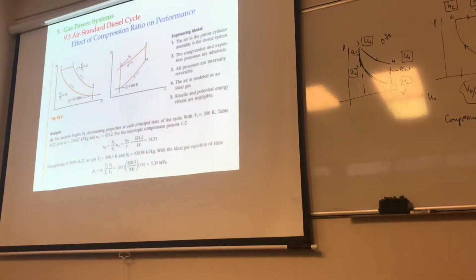So you need to jump to, and you know the pressure, you need 3 quantities, right? Before going to 2, because 1 to 2 is isentropic, what do we need to do? Remember that famous VR, right? When you go to table A22, for that first case, you need to read what is VR1. Then VR2 over VR1 is equal to V2 over V1, which is already known, so you can find what VR2 is, and this is what dictates the final state.